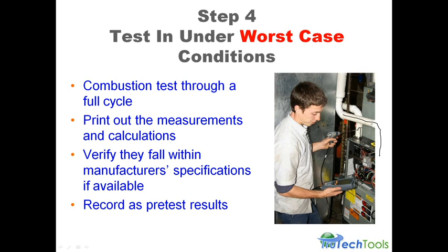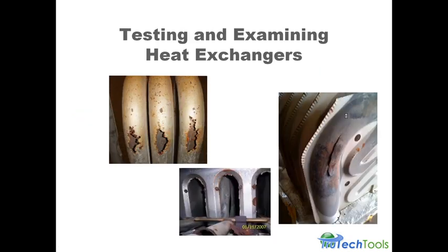And here this young guy is. He's got the door off the furnace. He's doing a CO test in the stack. The whole dynamics of combustion have just changed. If he would have put this door back on, what he would have found out is that I had a rag stuffed in this pipe and the furnace wasn't getting any combustion air and was producing massive amounts of CO. But with the door off, he completely missed the problem. And that was the exercise we were teaching.